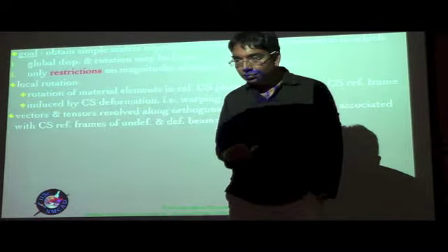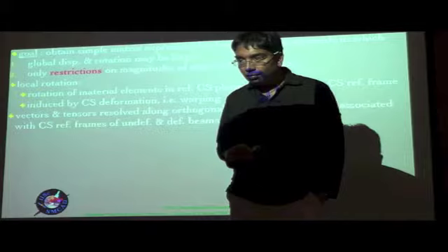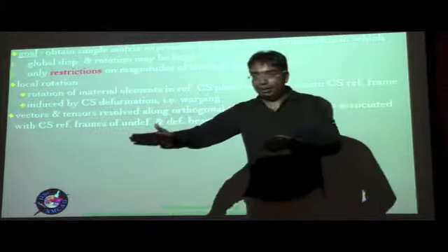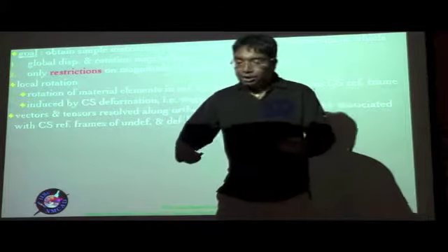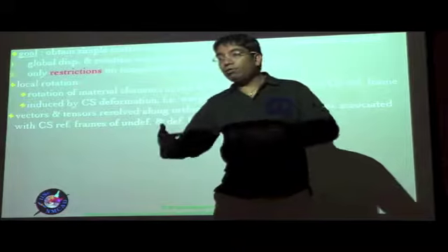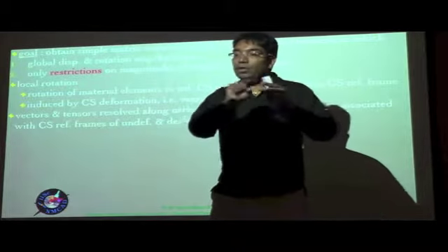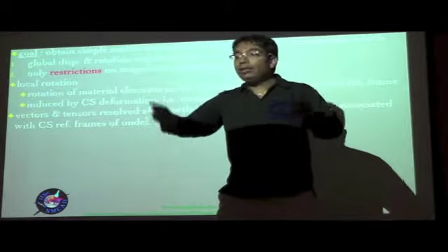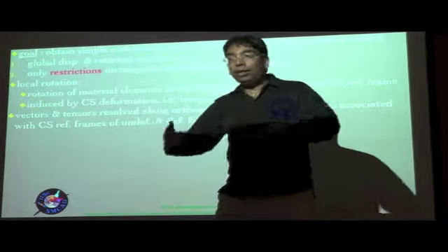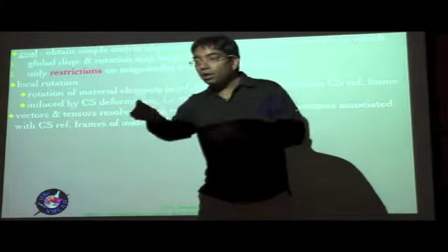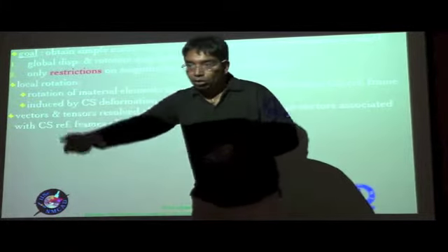the warpings in the second step or in the first step, I mean. First time. See, the restrictions apply on warping, right? See, the restrictions are not something which are assumed, but follow from the fact that the strain is small. So when we derive the expressions for the strain in terms of the overall warping, we can express the strain in terms of those components of warping, including local rotation.